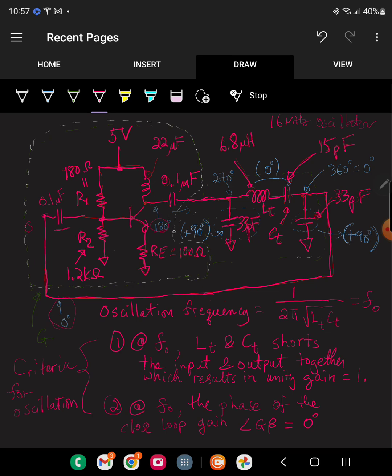It's just a short circuit. And then the first cap here, since you have a shunt cap, adds 90 degrees to the phase of the incoming signal. So since it is 180 degrees here, by the time it gets to this cap, it adds 90 degrees to the signal.